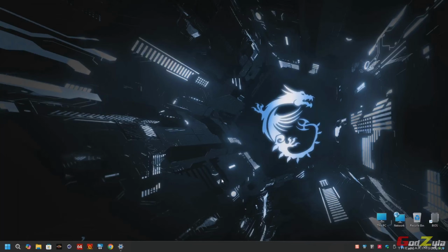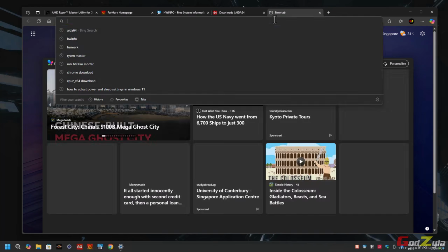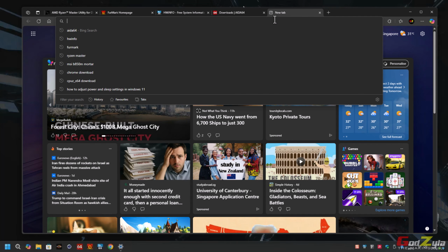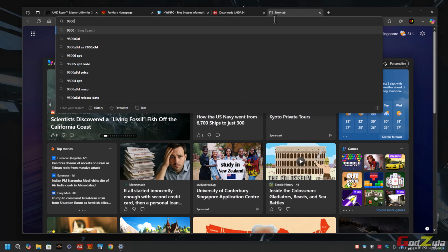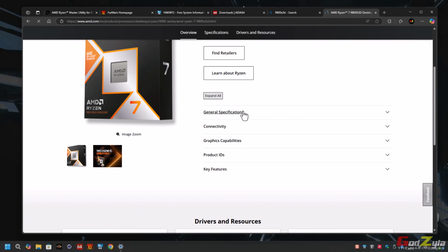First of all, to check whether everything is running properly and to take down the stats, you will first need to know how your processor works. I will just key in over here the 9800X3D. It's best that you write down your processor specs, so that when you do the tweaks on the PBO limits, the curve optimizer and the curve shaper, you know exactly what is going on.